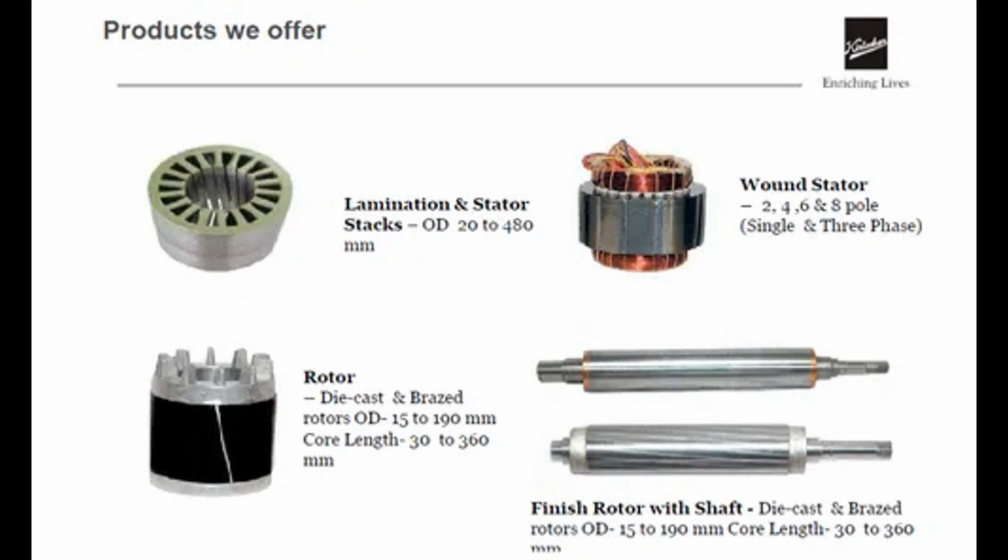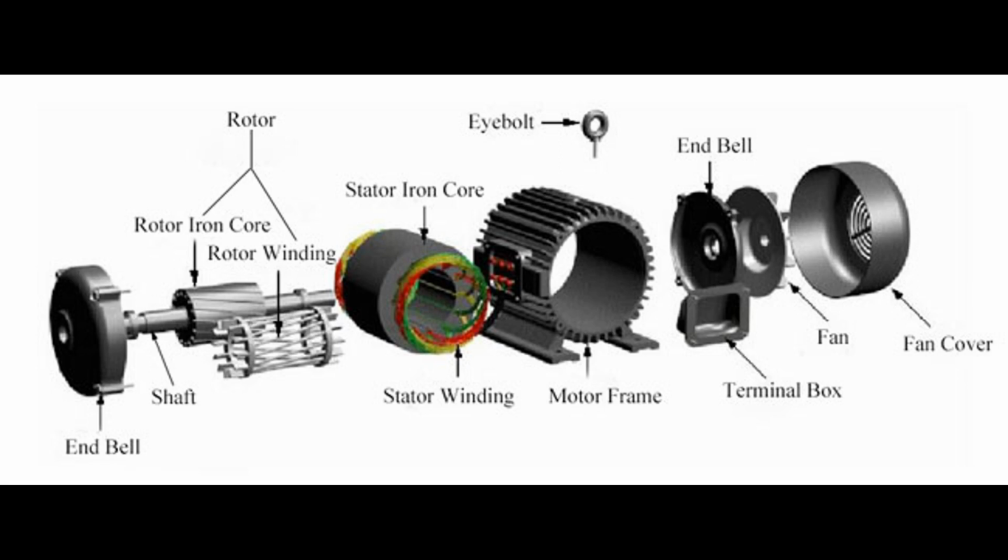In the context of an alternator. Rotor's magnetic field. The rotor of an alternator is designed to generate a magnetic field when an electric current flows through its coils. This magnetic field is generated due to the motion of electric charges, current, within the rotor's windings. The strength of the magnetic field is directly proportional to the current flowing through the rotor coils. Stator's role. The stator's coils are placed around the rotor, so when the rotor's magnetic field rotates due to the engine's mechanical power, it cuts across the stator's coils.